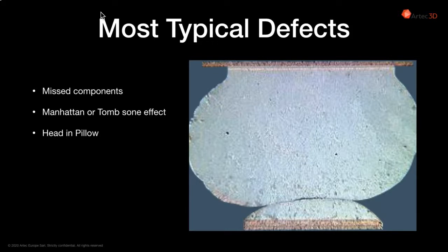It is a problem of the BGA components or other modern components that already have a solder on the lead. You can see the cross section of the solder joint, and you can see that these components have no real solder joint. It's 2 drops of solder without any reliable connection. The problem of this defect is that your device may work for a certain time and stop working afterwards because of oxidation or mechanical defect.